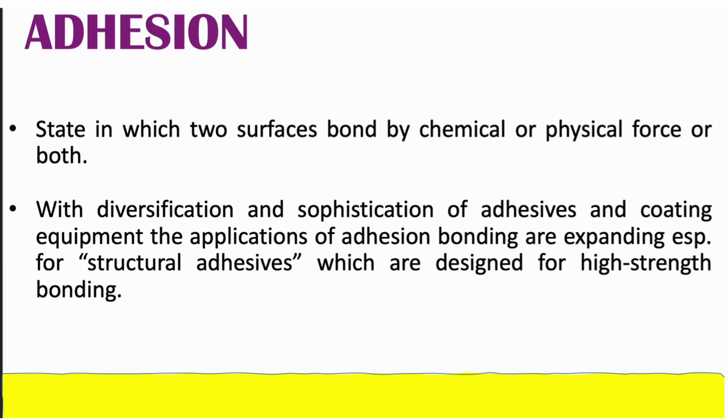With liquid adhesives it's very easy: we just apply and spread the adhesive because it is in the liquid state, easy to flow and spread on the substrate, and the adhesive's role begins without any other interference. But if we have a solid adhesive, then most of the time we have to melt it by heat so that it can flow and spread over the entire surface. So the solid adhesive must be melted by heat and the objects become bonded when the adhesive solidifies.